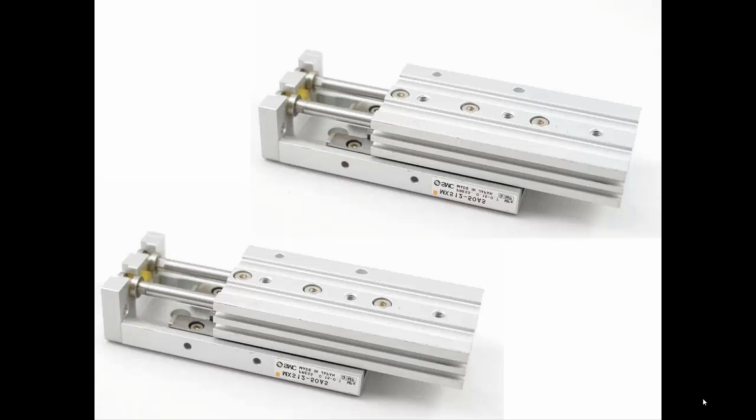What we have here are 2 pneumatic slides. In this case, the cylinder moves, but the base does not. So those 2 rods you see sticking out of the upper part, those are the rods. It's a dual rod cylinder. So the upper half of this slides back and forth under shifting of air pressure. Well, we could take one of these and mount it right on top of the other one, and so the bottom one moves the top one back and forth, and then the top one moves its slide back and forth. That gives you 4 positions. Now, if these are both the same length, you might end up with 3 positions, but we'll assume 4 positions.